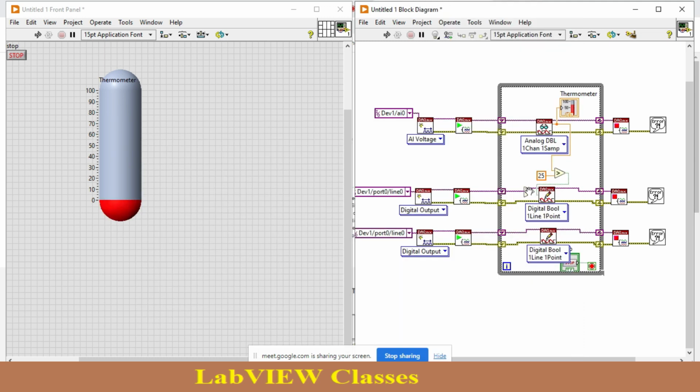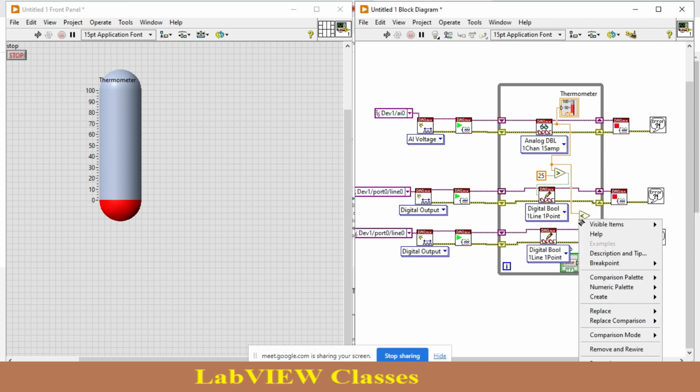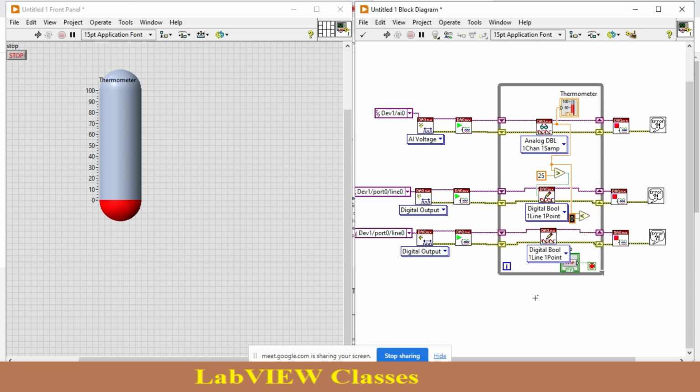So when this input temperature, this initial temperature, is less than 20 degrees Celsius, in that case it will generate a true signal again, and in this case I am using another pin. So using this you can create your own temperature control method for your chamber. Okay.